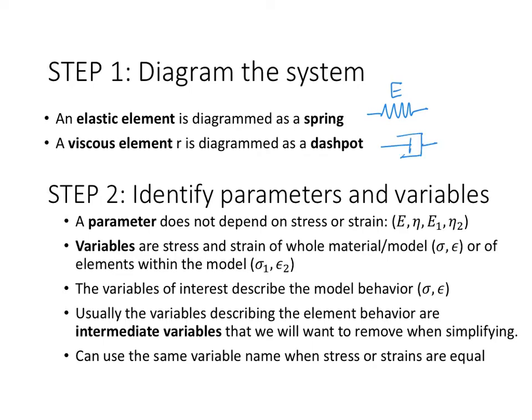Think of that as like a bicycle pump where there's a cylinder and a plunger that the fluid has to move around to go past, and so it's viscous. And we use the parameter eta for this. E, of course, is in pascals, and eta is in Pascal seconds. That's the viscosity. So the elasticity and viscosity. So we have these two types of elements.